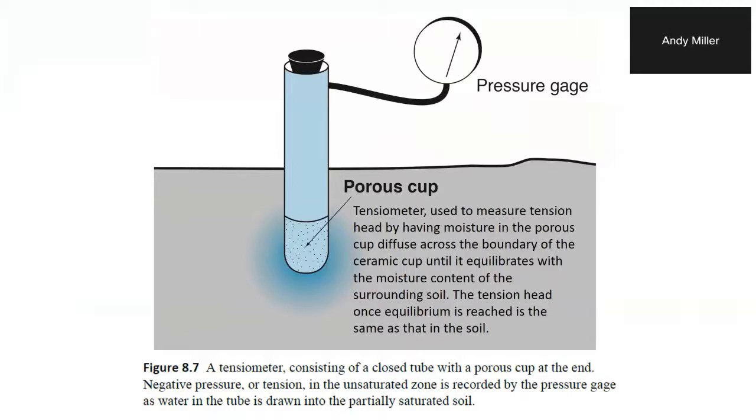So we talked about piezometers, right? A piezometer is basically the equivalent of an observation well. It's not open through its entire depth, but just at one location, because what it's doing is measuring the head at that location, and the height to which the water level rises in the piezometer tells you what the pressure head plus the elevation head was, the elevation of the observation point plus the pressure head that raises the water level to some point above that. If you have those kinds of observations, you can use those both to compare.